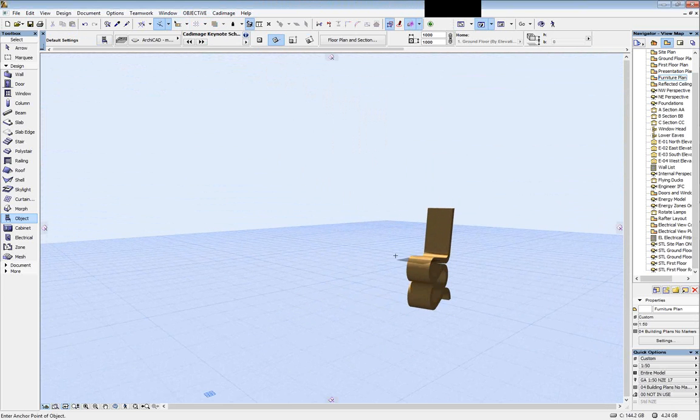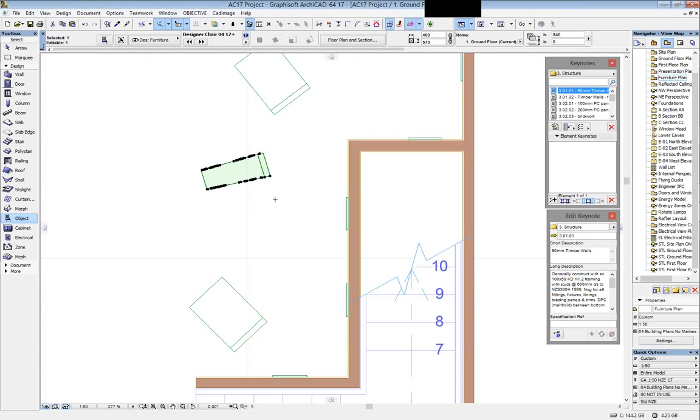Previously, this worked so that you could rotate, cut and move timber pieces to build massive oak frames. So this was a tool very specialized at building timber frames, but a lot of people have seen this tool and what it could do that ArchiCAD has never been able to. And they wanted that functionality, but they didn't need a lot of the fancy scheduling stuff that it can do for timber frames. So the likes of split, rotate, bend, this is all part of Objective, and it just allows you to cut up and move objects in any view that's most appropriate. It's a useful little tool.